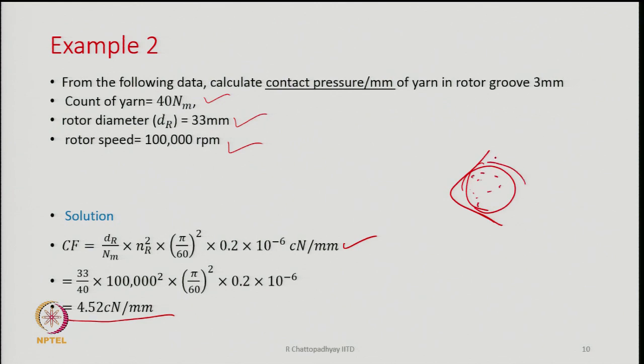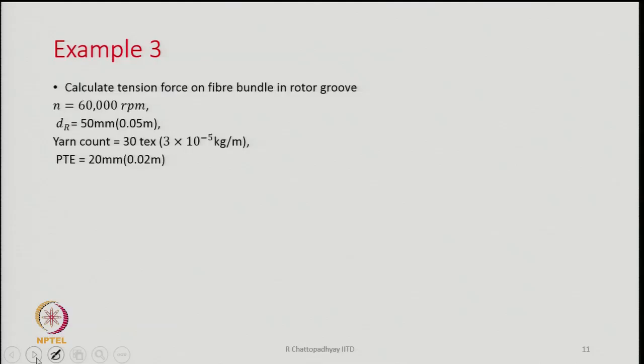it has to rotate, and these are the friction points. The yarn may not be circular at this point when the fibers are not really twisted; it may be flattened and take a shape like this. If it is taking a shape like this, obviously with a lot of centrifugal force acting, a lot of friction will be there, and one has to overcome that friction. The torque should be sufficient to overcome this friction and twist the band of fibers. This problem is not there in the case of ring spinning.